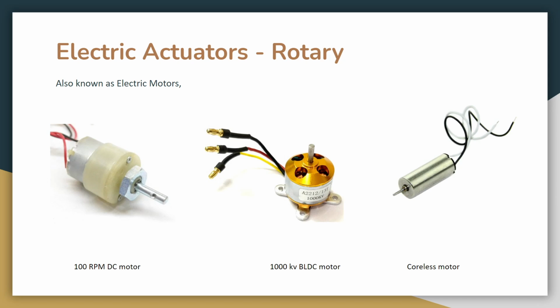If you want the speed as angular velocity, it's 2 pi times the rpm divided by 60. That's the fixed angular velocity this motor is going to have when it's rotating continuously. So you can never force it to change its speed to half or a quarter of it. That's why it comes under synchronous motors. It's not a DC motor. It takes in 3-phase AC, and then it's driven.